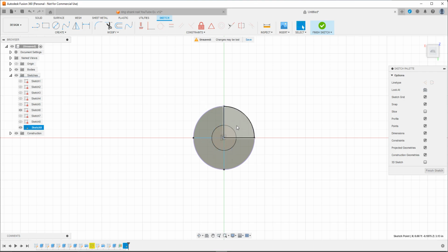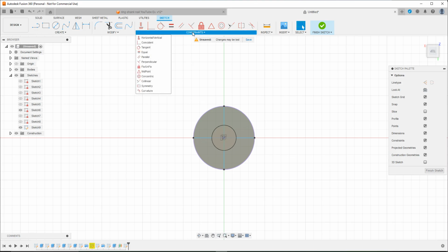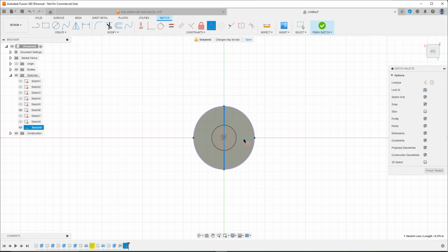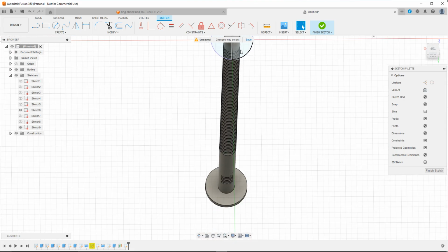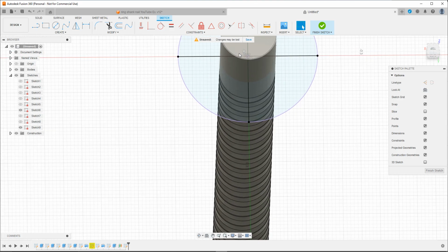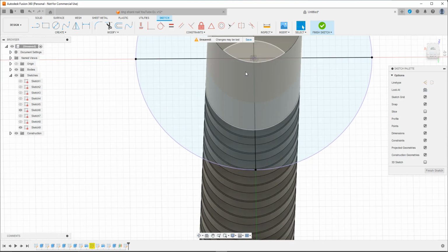And we are going to midpoint constrain these two together. Midpoint of this and this. Now we're locked. Now it's not going anywhere. So, what that did was create 4 equidistant points a set distance down from the top of the nail.